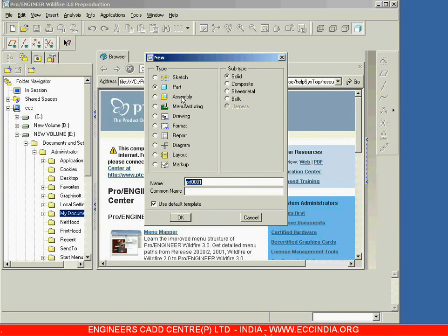Now after creating the assemblies and after creating the drawings, once again if I open the part and modify anything there in the part, those modifications automatically will reflect in the assembly as well as in the drawing. That means when I am changing in one module, those changes are automatically updated in the other modules. So this kind of connection between module to module is known as associative. So this is about the second definition, and the third one is parametric.